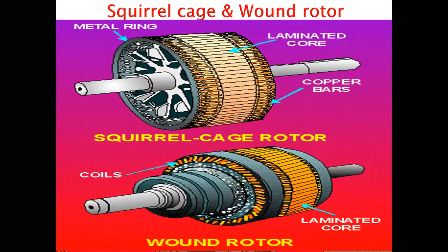So here, when we use the squirrel cage induction motor, the rotor of the three-phase squirrel cage induction motor looks cylindrical in shape, the same as we are saying about the three-phase induction motor. And here, the slots are not parallel to each other, but they are skewed. These slots. So here we can say that skewing prevents the magnetic locking of the stator and the rotor teeth. Thus the working of the three-phase induction motor is improved and it becomes less noisy.